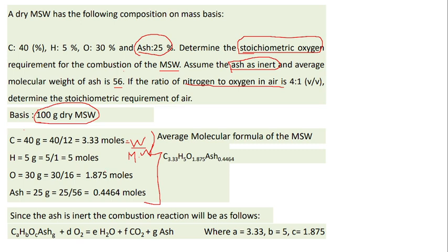With these moles, we can easily find the molecular formula of the municipal solid waste. Before going for the stoichiometric balance, these moles are required to write the equation. Now we have found the molecular formula of MSW. So write the stoichiometric equation.